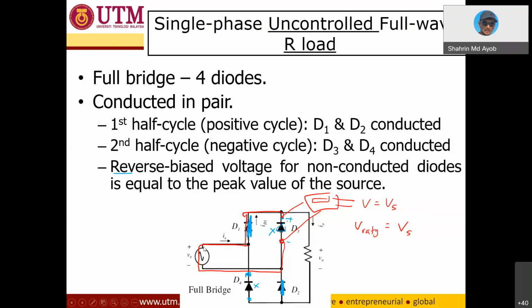For example, I'm using a voltage source of 300 volt. Based on this analysis, the minimum rating should be 300. For precaution, maybe I use a 400 volt rating diode. So no need to buy 2 kilovolt or 4 kilovolt diodes, it's a waste of money.